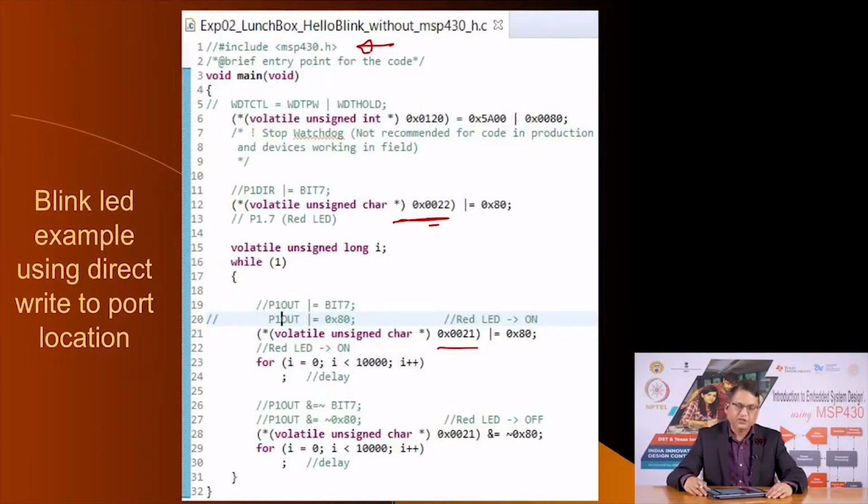In fact, MSP430 is not only a von Neumann architecture, but you can also see ports in two ways. One is called actual ports and the other is called memory map ports. In MSP430 these ports are mapped into the memory map, that is the port addresses are like memory locations, which means any port can be seen as a memory location. In fact, the point of this exercise was to show that a port is also a memory location and we can manipulate the information in the case of MSP430.